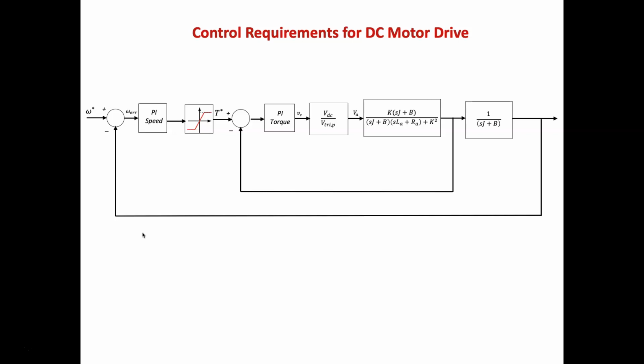So what should be our control requirements? In most cases, we want the response to be as fast as possible, with minimum oscillation and good stability. To fulfill these requirements, it is sufficient for us to use the Bode plot. Large bandwidth, limited by the switching frequency of course, translates to fast response. Good phase margin, typically larger than 65 degrees, translates to good stability with less oscillation.